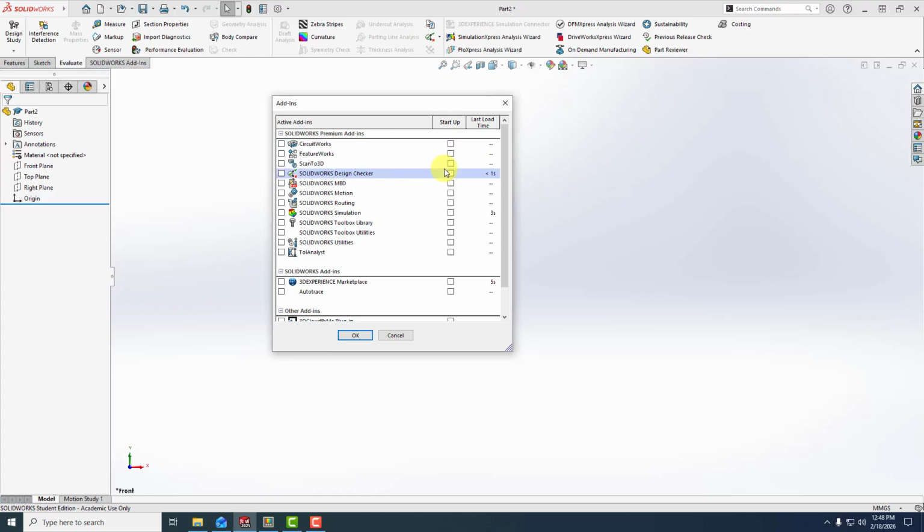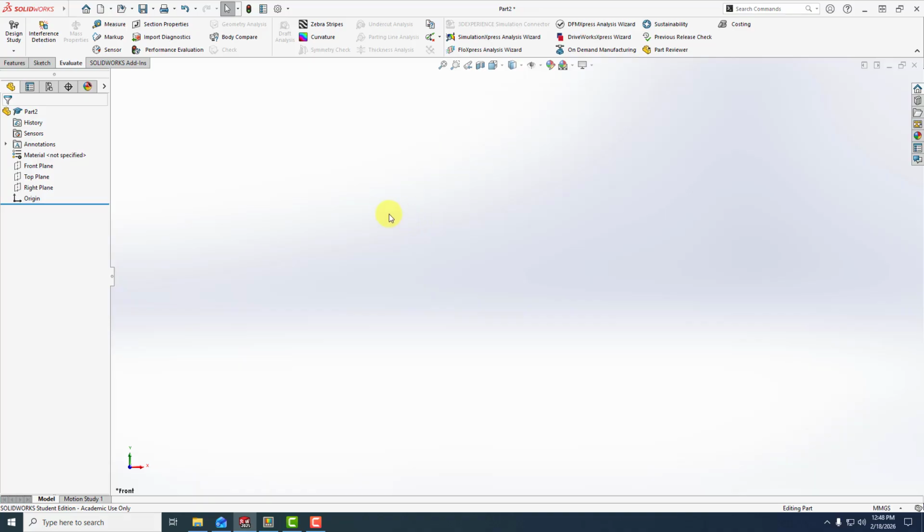When you installed SolidWorks, you might have SolidWorks Motion and Routing. There might actually be CAM tools and all of that. So you go in here under startup, you can click those off so that you're not taking the time for loading all that up every time SolidWorks loads. All right, so that's all I have for the setting up of SolidWorks.